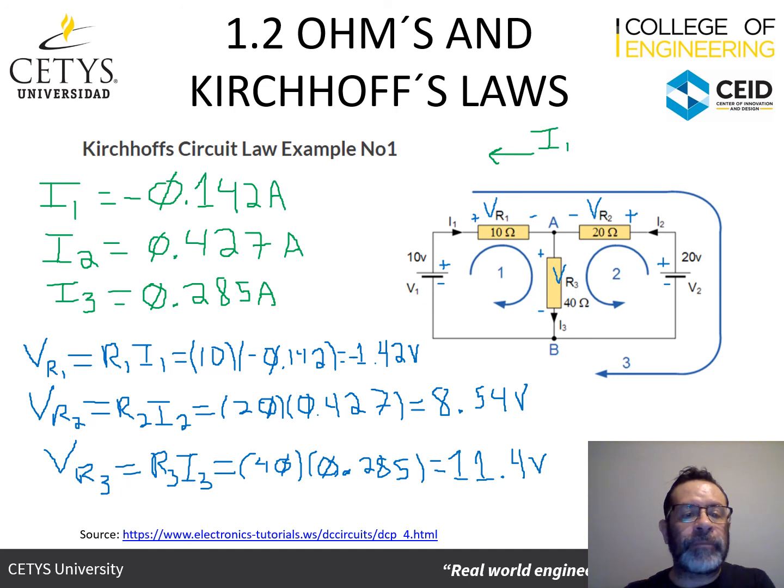And in this case, the voltage in R1 is also negative. That only means that since the current is going this way, then actually the voltage in R1 has this polarity, which is the opposite polarity as the one we had identified. And so this way now we have all of the values of the elements in the circuit.